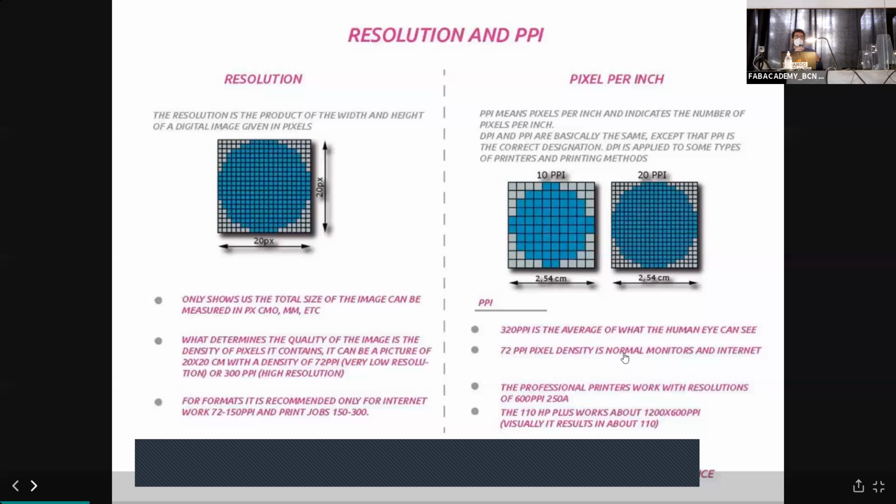Pixels per inch shows the amount of definition. If you have 1 inch, that is 25.4 millimeters, for those not familiar with imperial, and you have 10 ppi, you have 10 pixels. Those photodiodes or pixels will be bigger, which means they are able to capture more light.